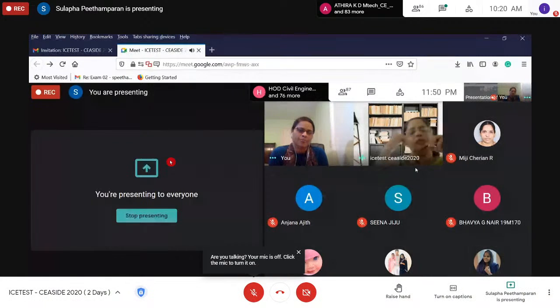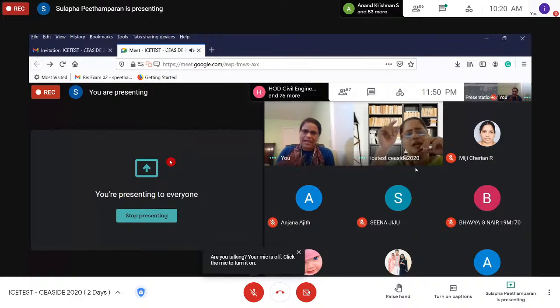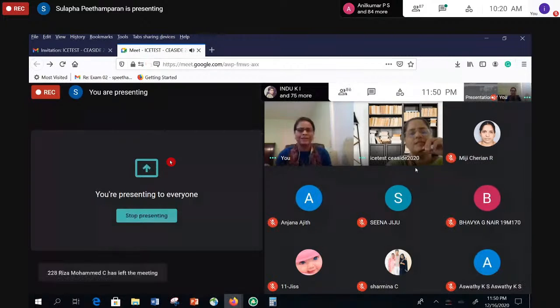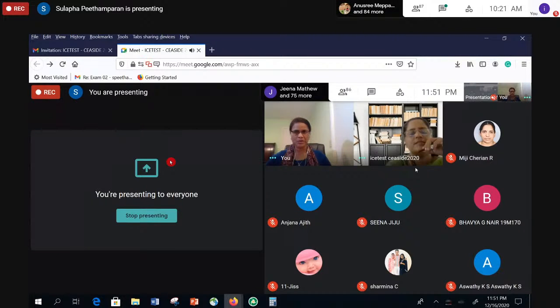What about the class C fly ash? In geopolymer, we can use that one. Yeah, we can use both class C and class F. In class C, you have calcium in it, so it is even more fast setting compared to class F fly ash. There may be a little bit delay in class F, but class C is better with respect to setting. And sometimes you have premature setting if you are using class C with a very high dosage of alkali. Okay. Thank you, ma'am. No problem.